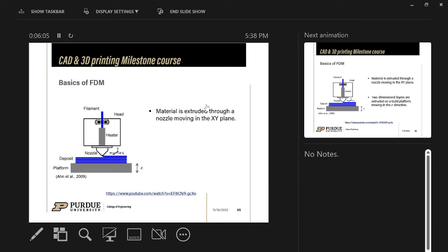Now, material has a thickness of typically millimeters. Now, if you want to make a part that is inches tall, right, you're going to work virtually in planes, right? So you're going to start off on plane 1, and you're going to lay down a single layer. And that's all you can do in that plane, right? Because you can't really go up. Well, you can, but when you go up, you basically change your whole level, right? So you lay down one layer at a time, and then you move up to layer 2, and then you lay down material on top of said layer, and then you just keep building yourself up from the ground.